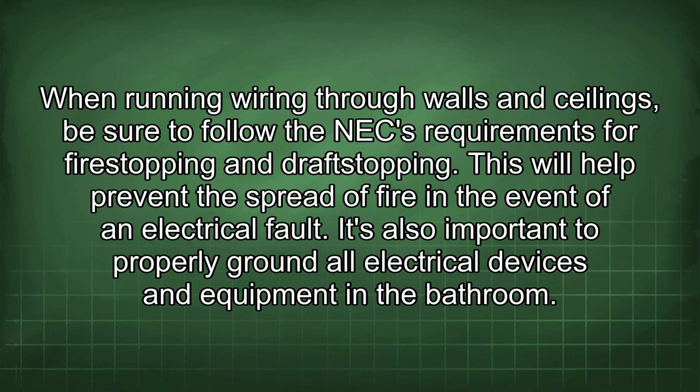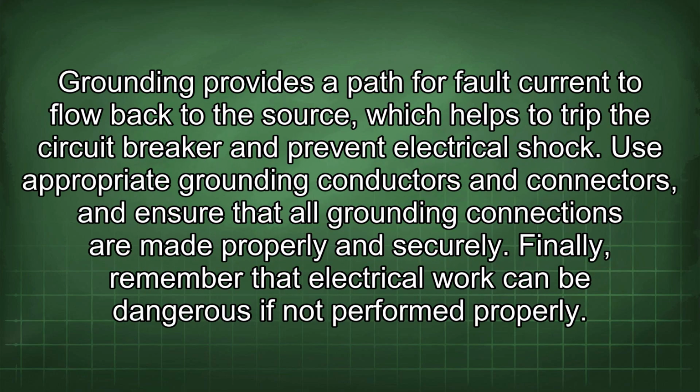It's also important to properly ground all electrical devices and equipment in the bathroom. Grounding provides a path for fault current to flow back to the source, which helps to trip the circuit breaker and prevent electrical shock. Use appropriate grounding conductors and connectors, and ensure that all grounding connections are made properly and securely.